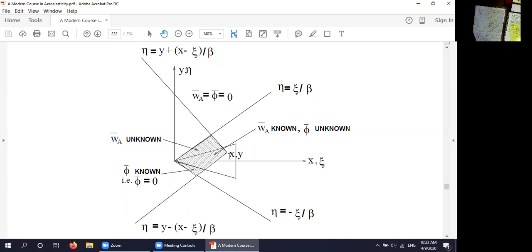And we would like to know what the velocity potential is there. And then we can always use Bernoulli's equation to compute the pressure once we know the velocity potential. But now we need to keep track of what we know and what we do not know, and where we need to know it. It's supersonic flow, so for x less than 0, or its dummy variable c, where c is less than 0, the flow is undisturbed because this plane is moving at supersonic speeds, faster than the speed of sound, and the flow field is not disturbed ahead of it.